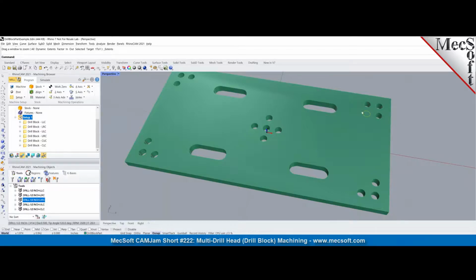So even though it's not being drilled, in our CAM system we have to create an operation that creates a drill toolpath that goes right there. So that's why I've created this circle to represent the location of the anchor bit, and I've created my drill operation to drill that hole. And then I'm using the URC drill bit that I've already created.